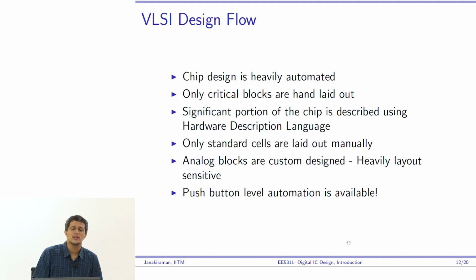Okay, only the critical blocks are hand laid out, which in this course you will do only hand layout, you will not do synthesis. A significant portion of the chip is described using hardware description languages like Verilog and so on, right? Only some select things called standard cells, I'll tell you what they are, are laid out manually. Analog blocks are usually custom designed, right?